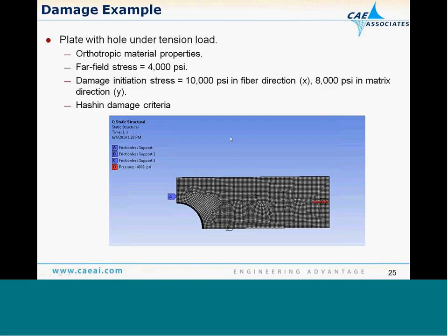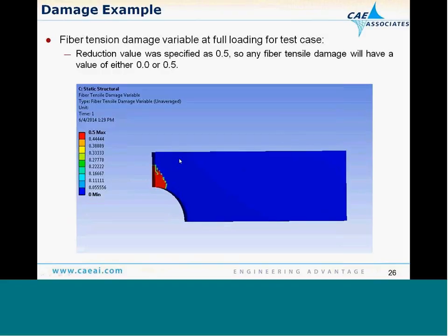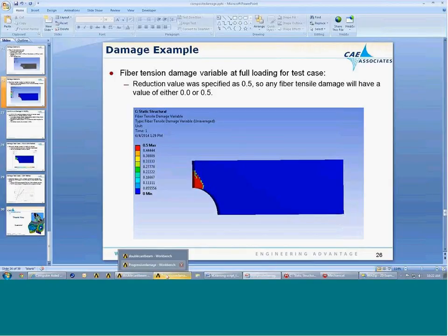So let's take a look at a model here. We have a plate with a hole. We put it under load, and if I go in and I say, okay, which elements become damaged, we can see that these elements have become damaged and their stiffness has been reduced by half. Let's take a look at that actually inside of Workbench.